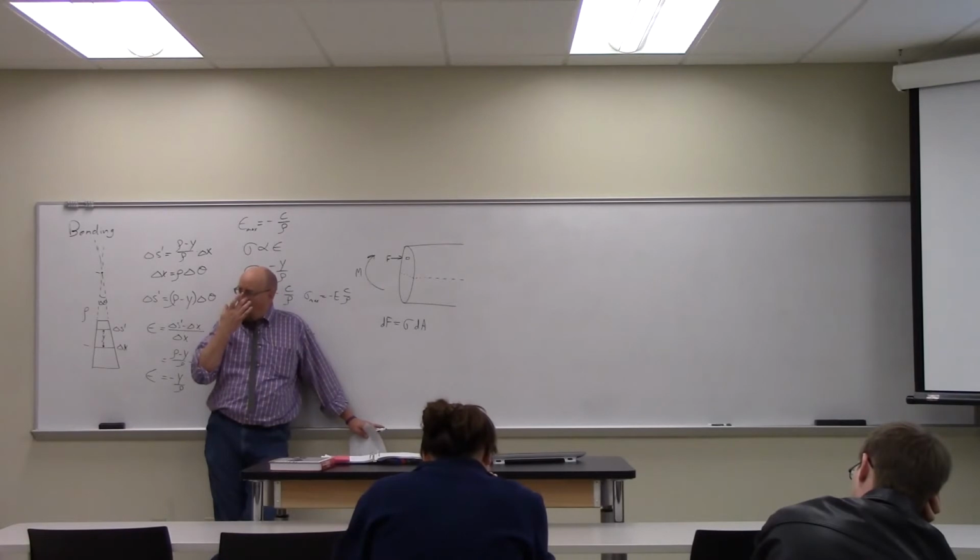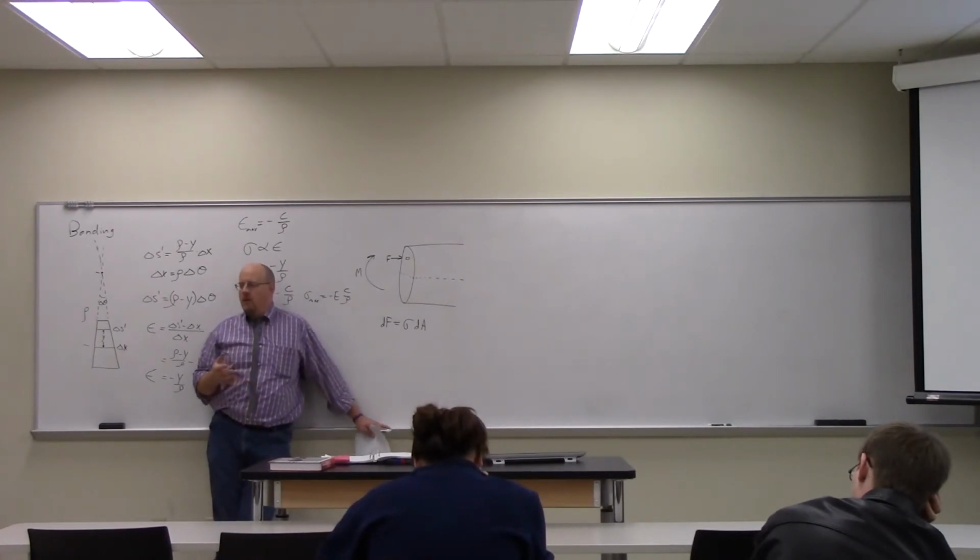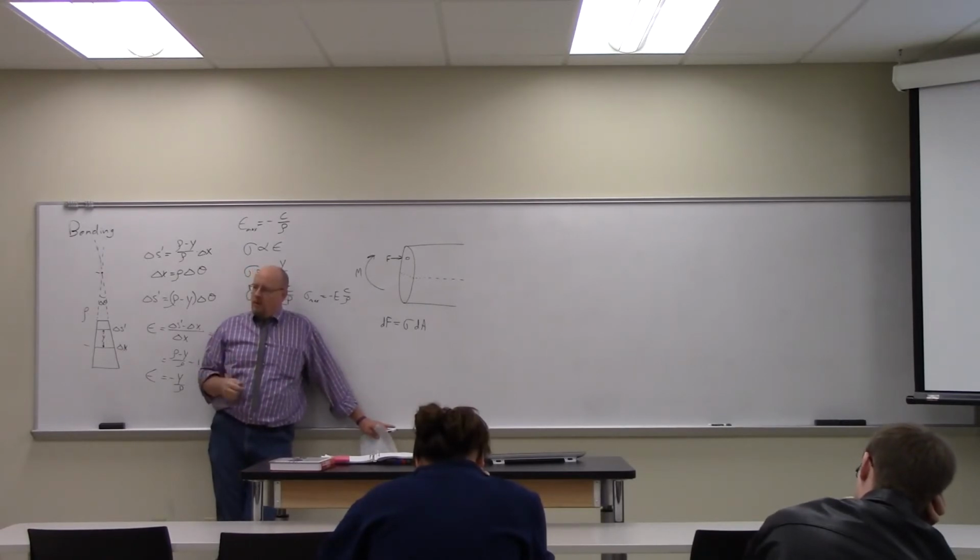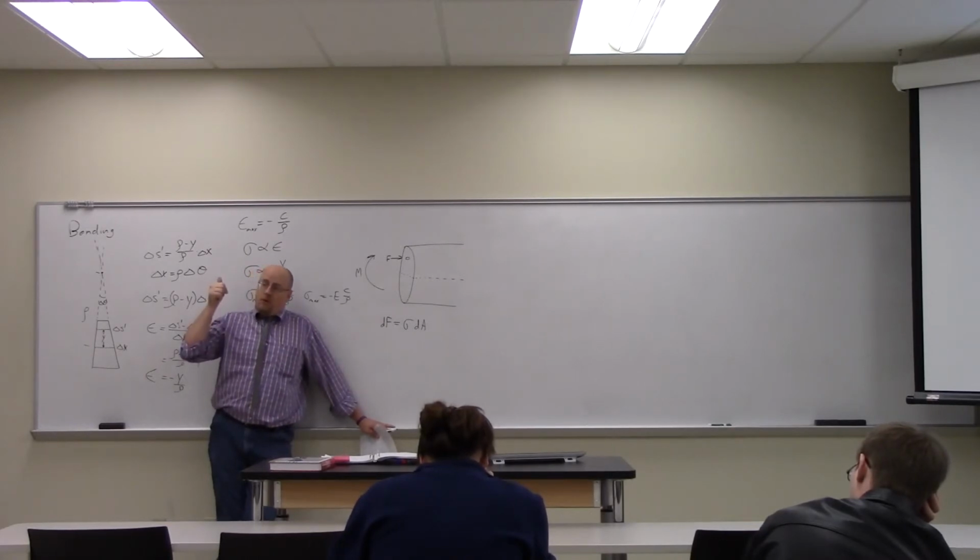Yeah, I guess the thing I was saying is because we said there's no shear stress in the beam, but I was thinking if there's a force applied perpendicular, you would think there would be. Right, so this is not a bending moment resulting from an applied force. This is an applied moment. We've looked at what happens when you apply forces already, and we've looked at what happens when you apply torsions already. Now we're looking at what happens when you apply a bending moment. Then we'll have covered all the bases for all the things you could have applied.